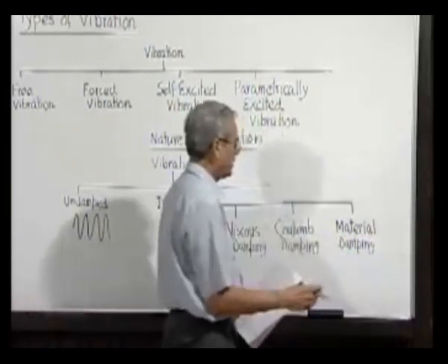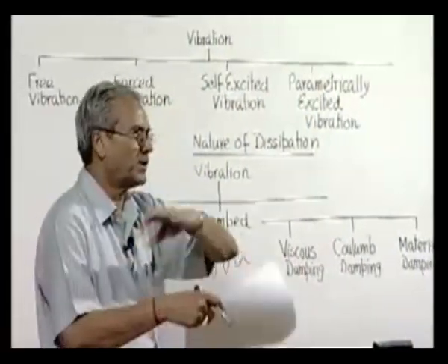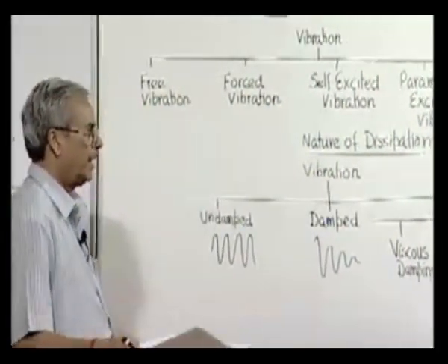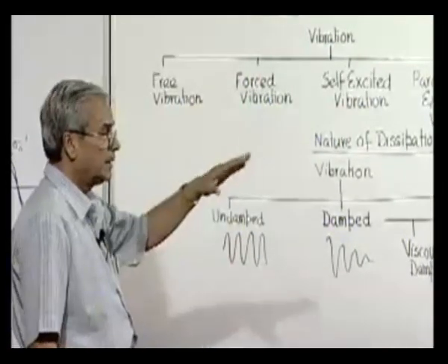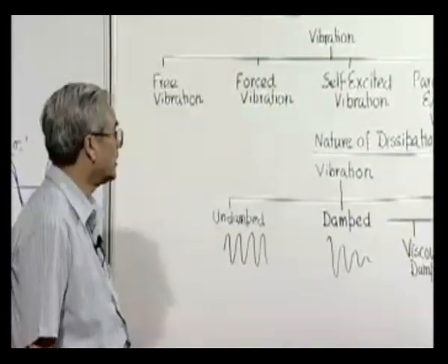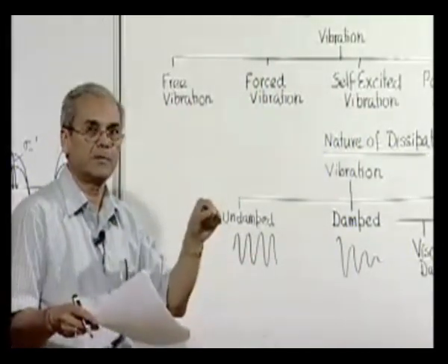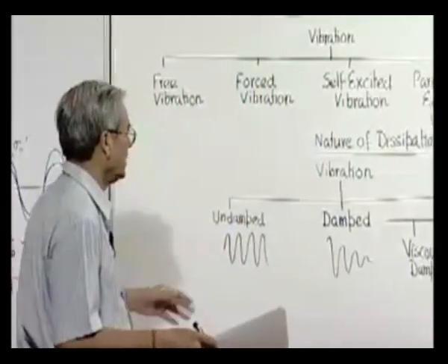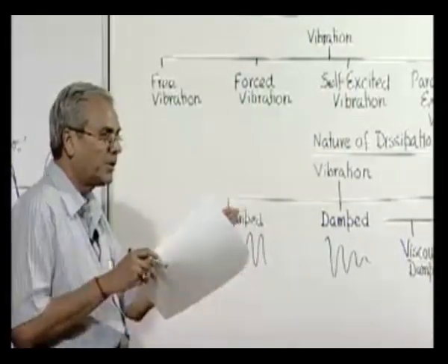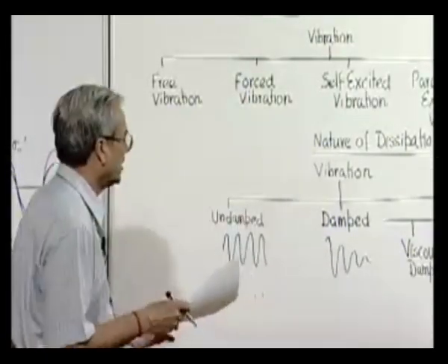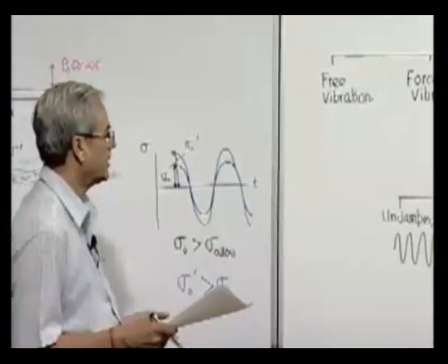It means, we can see that if we take a piece of beam in space where there is no fluid, no air, and we just vibrate it and leave it in space, we will still see that slowly the vibration will reduce. There are internal mechanisms within the material, just like hysteresis. It is also called hysteretic damping, and the rubbing of grains and other crystal boundaries involve a certain amount of energy dissipation.